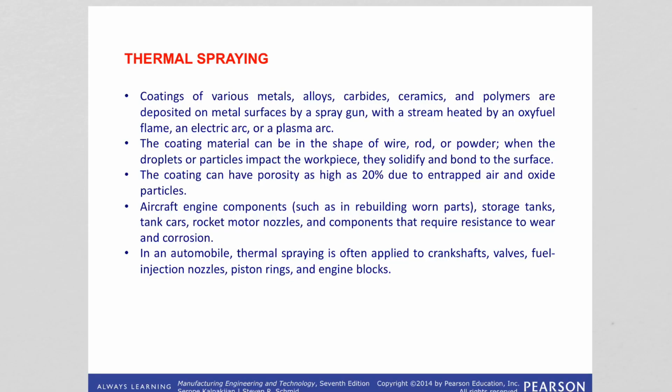The surfaces to be sprayed are first cleaned of oil and dirt, then roughened by, maybe, grit blasting to improve bond strength between the surface and the sprayed material.